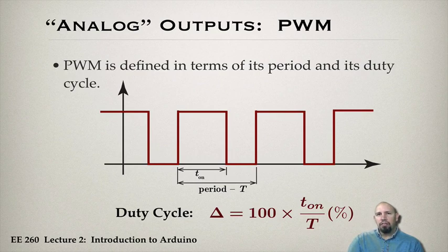So when you have a duty cycle, for example, of 50%, that means it's on half the time, off half the time. And so you have these pulses that are spaced like that. Okay, so that is the concept of pulse width modulation. Now, this idea can be used to provide, in a sense, a variable output, kind of like analog. So analog actually takes on all these values between, for example, 0 to 5 volts, but we can kind of simulate that using pulse width modulation.